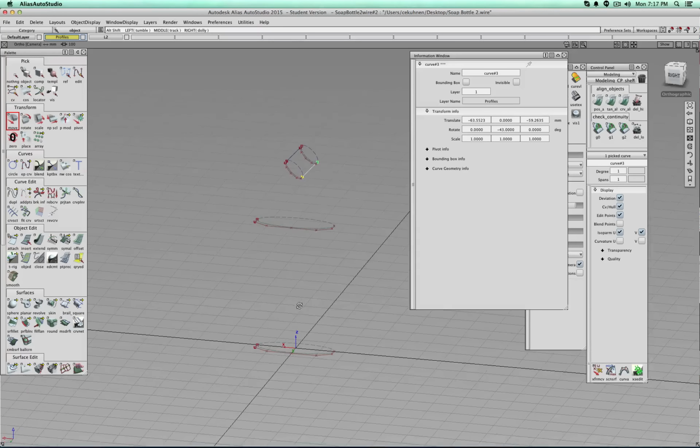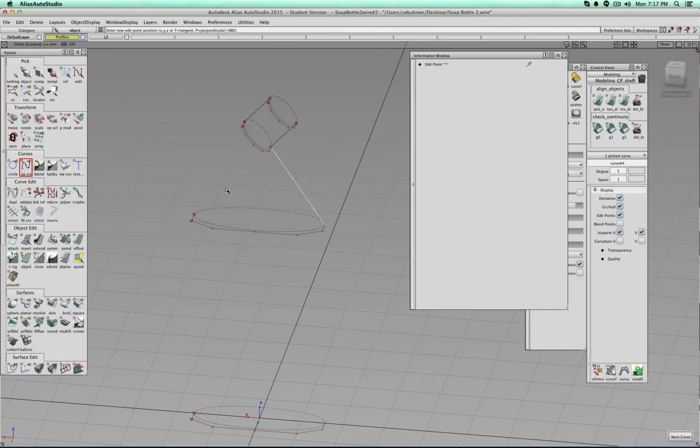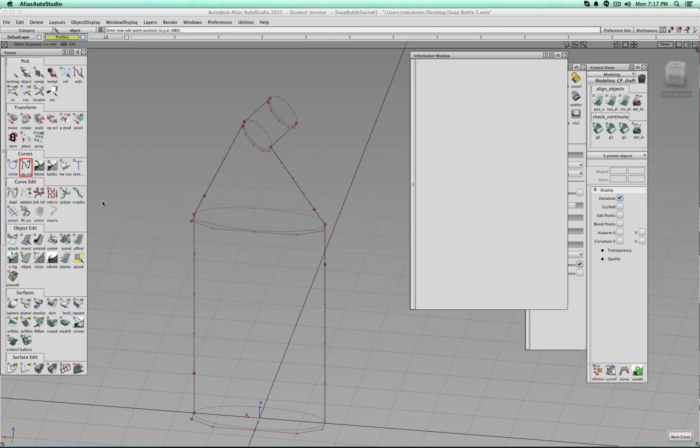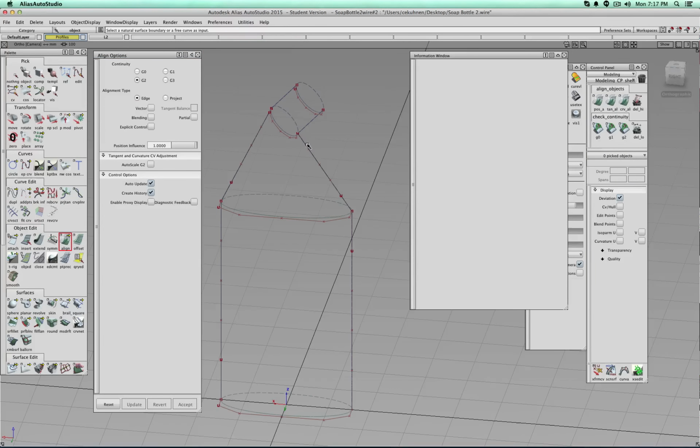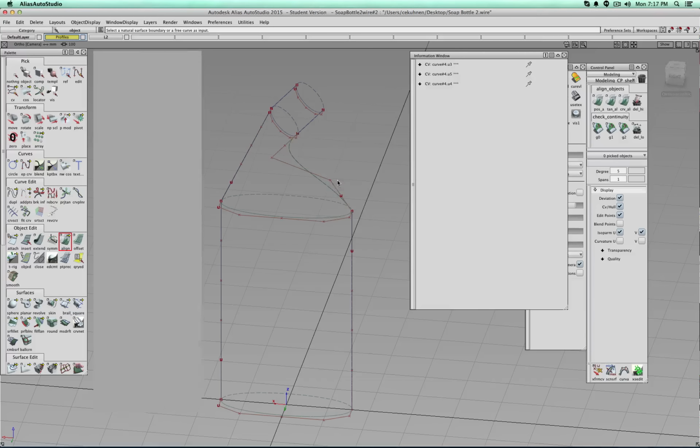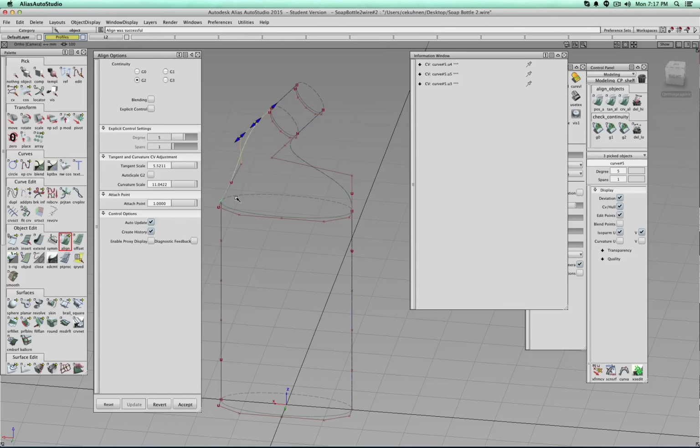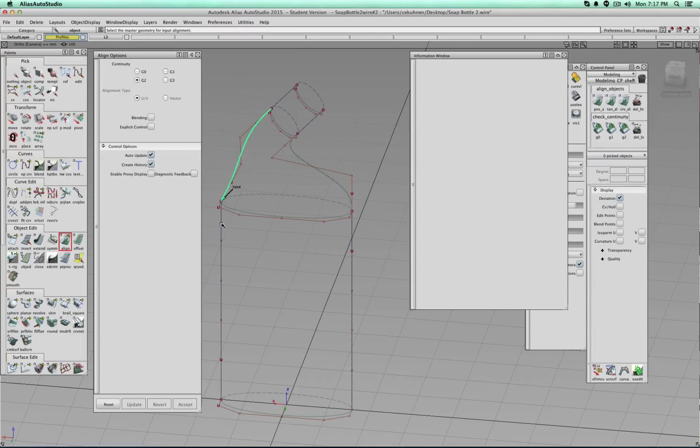Okay, so now for example I can maybe create myself a degree 5 curve, control click, nothing, control click, nothing, and I do one here for the moment, because the main reason what I'm doing here right now is I'm going to create myself a reference curve. So this one to this one, there, here and here, here to this line, and you see those are all G2 alignments.